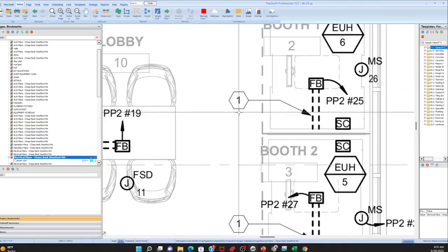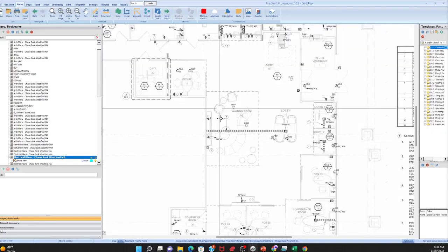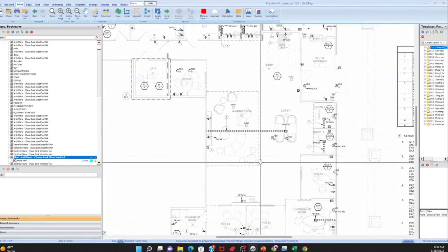One thing I look over before you get a set of construction documents and you know you're going to bid on the set: make sure you always review the specifications. The specifications are the written words that go with this project that tell you the type of material, how they want you to install stuff, and if they want submittals.